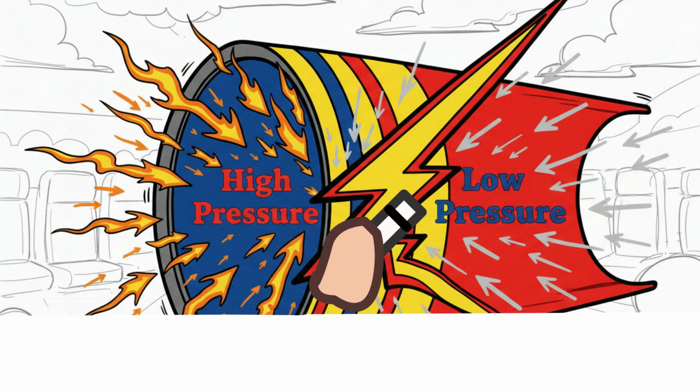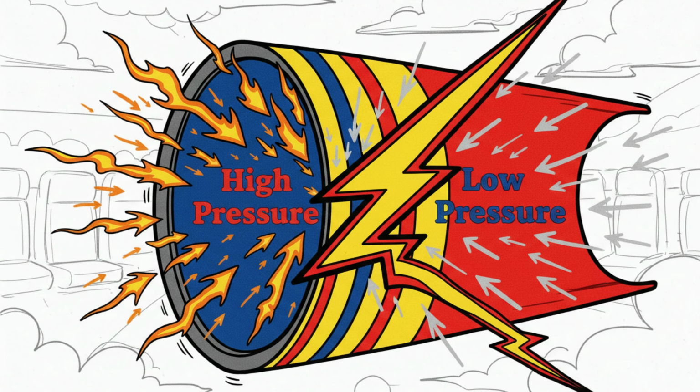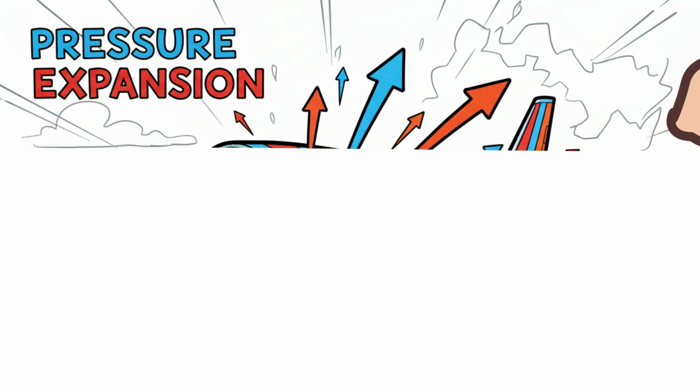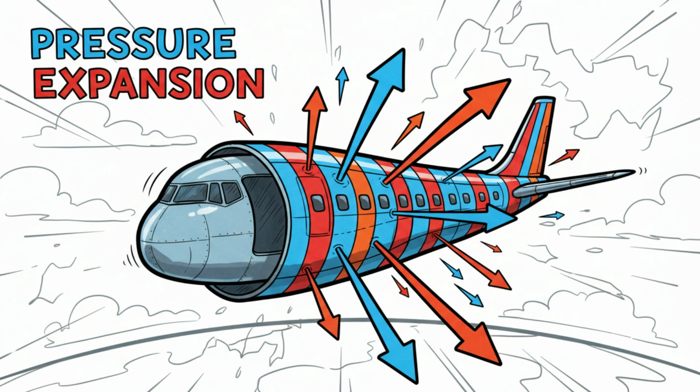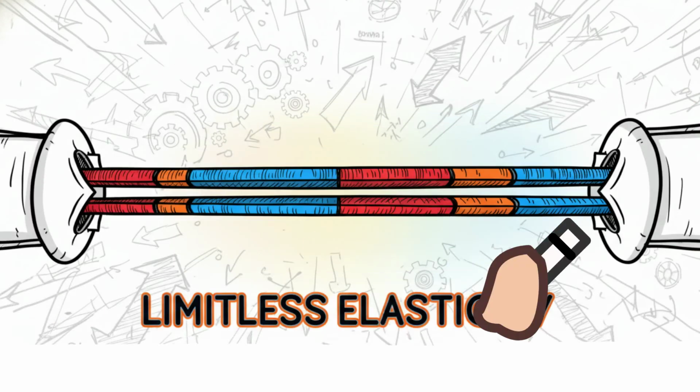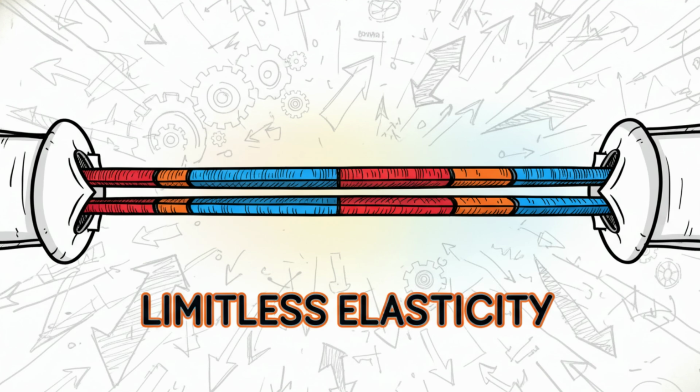To visualize it, think of the stress flowing like water in a river. An oval shape lets the water glide smoothly around it. But a square corner is like a sharp 90-degree rock wall. The water would just slam right into it. It slams into it, and all that force builds up. It concentrates right on that single point, the corner. It's incredible that a few millimeters of a curve can make that much of a difference.